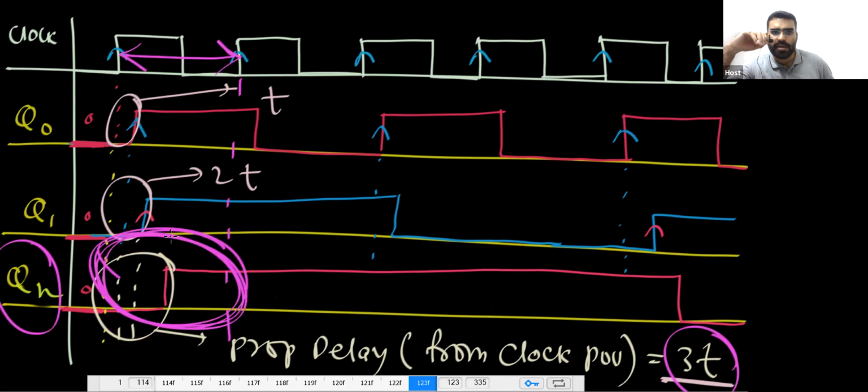But if you increase the number of flip-flops in the ripple counter beyond a limit, this settlement will not happen. The next clock edge will come, but you are not settled. It's like your next weekly quiz will come, but you have not covered the pending chapters. You are not ready, so uncertain behaviors will start happening. The next clock edge will come, but your circuit is not settled.